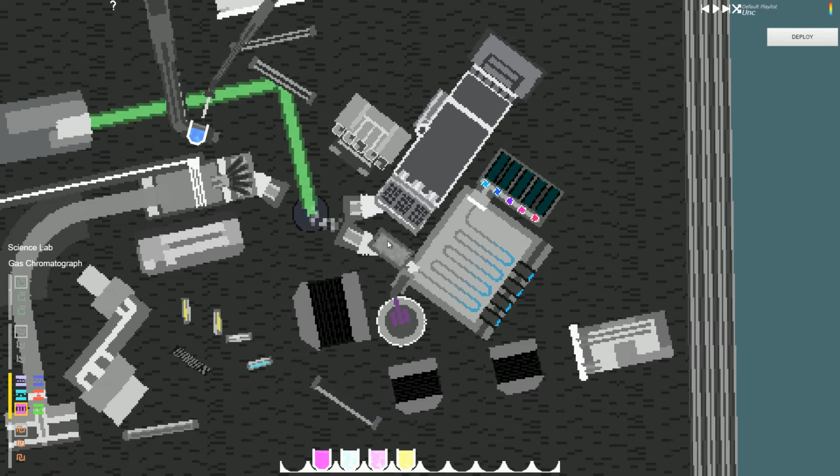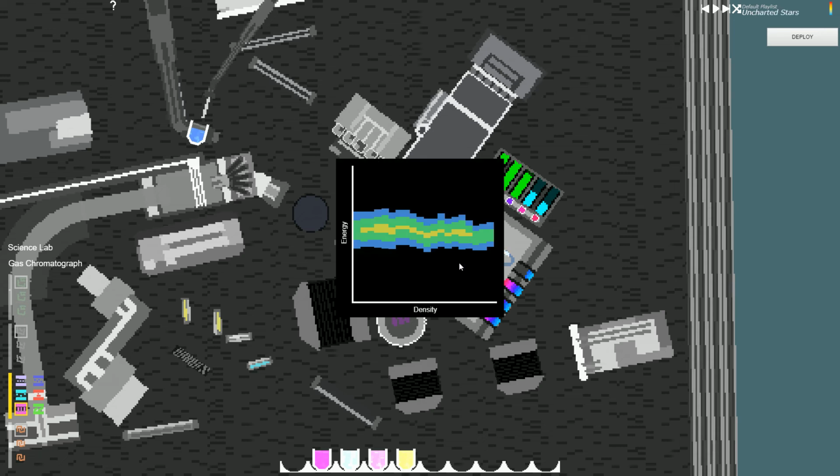You can left-click to raise the temp of each heat control, or right-click to lower it. The detector's data collection is driven by the final temp of the gas as it arrives at the detector. The vaporized particles in the gas sample have an effect on the specific heat and the heat capacity. Specific heat is how well the sample can retain the heat it carries, and heat capacity is a measure of how much energy is required to actually change the temperature of the sample. The challenge is to try to find the right temp settings on the 4 dials to get a good diverse data set at the end.